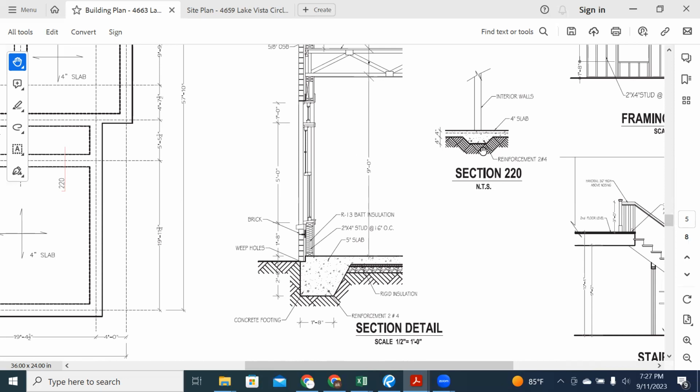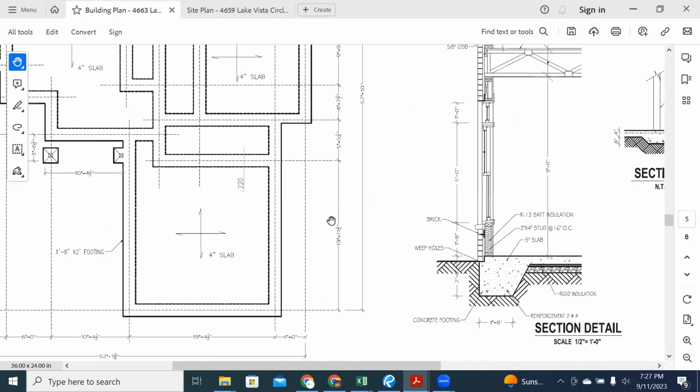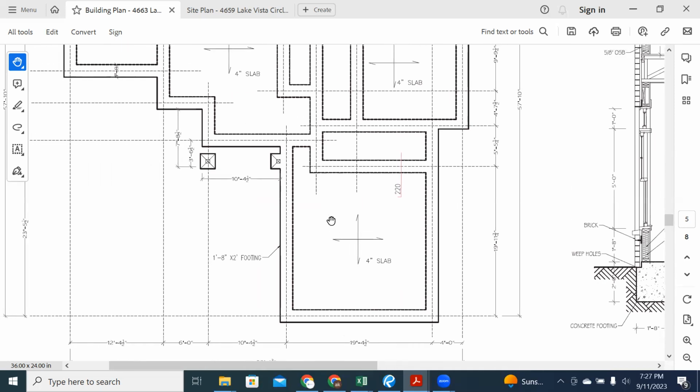But in the cross section of that interior wall, you still have what? Your 2 number 4 rebar for reinforcement. So you're still going to have 2 rebars lying in here. Now, those rebars actually will be lying on top of your plastic. If you saw the video, that's what it is. So what happens when you have that? Why do we have that?